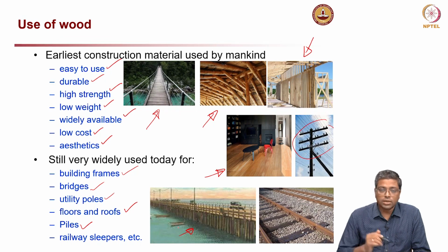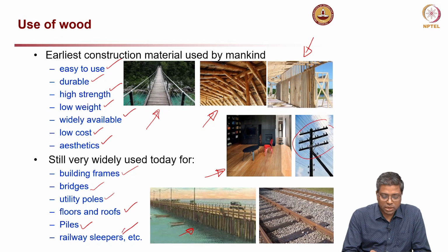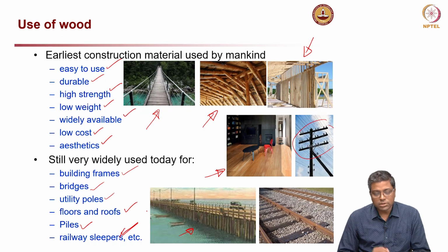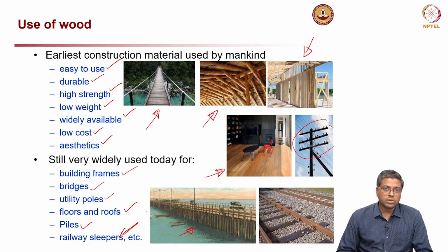And then piles for bridges or anything which is going into a water body, and then railway sleepers. This is widely used, but now again it is changing to reinforced concrete or pre-stressed concrete systems because of the higher load or better capacity requirements for the sleepers, but wood has been used widely in earlier times.